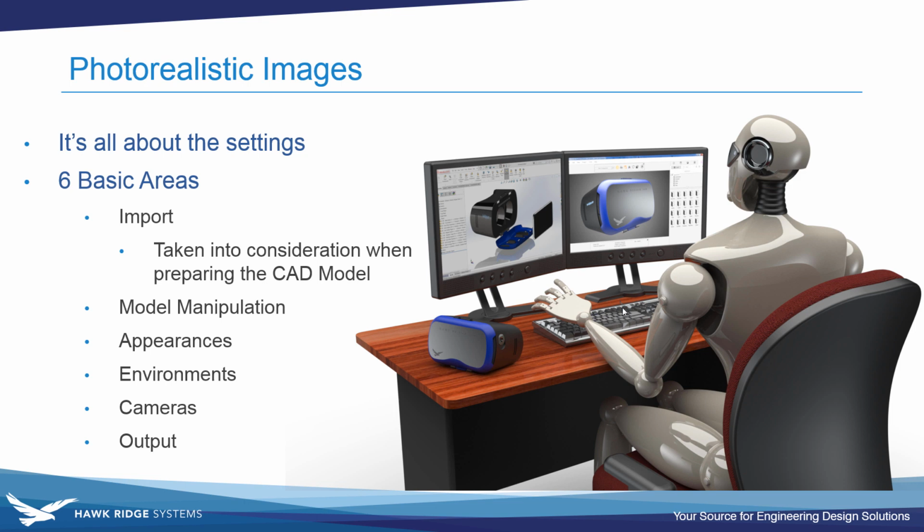All right. The other way is the appearance method for importing. And that is the quickest way, because basically as you create appearances in the CAD model of what you want, when you import that into Visualize, it will give you just those things as parts in your model tree within Visualize.